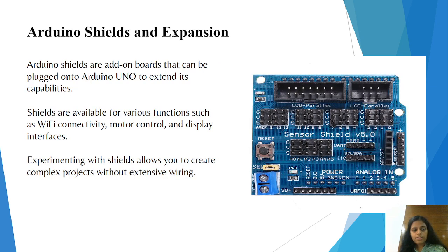Next, let's know what are Arduino shields and expansion. Arduino shields are add-on boards that can be plugged into Arduino UNO to extend its capabilities. Shields are available for various functions such as Wi-Fi connectivity, motor control, and display interfaces. Experimenting with shields allows you to create complex projects without extensive wiring. So this is Arduino shields and expansion.